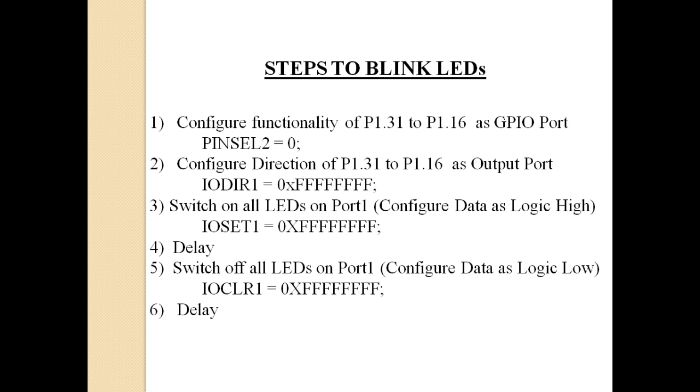So the LED will be on, some delay will be given. The LED will be off, again some delay will be given. Right? So it will ensure that both on and off states stay in my eyes for at least half a second. Then only I will be able to see the blinking effect. If you are removing these 2 delays, I can see that the LED is always on. That on and off state I will not be able to distinguish. That is why you are adding the delay.